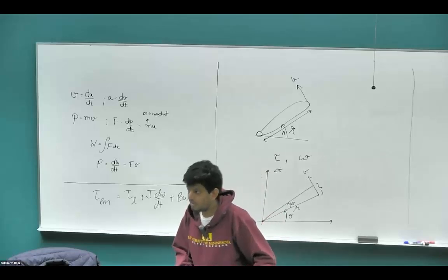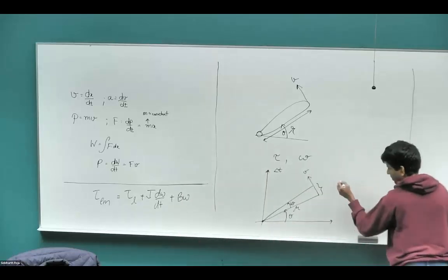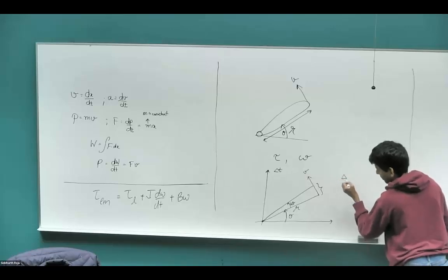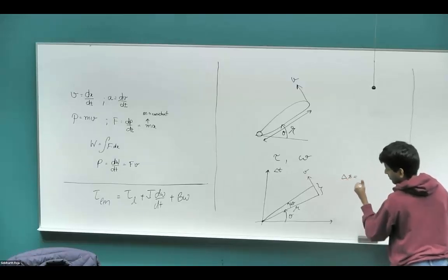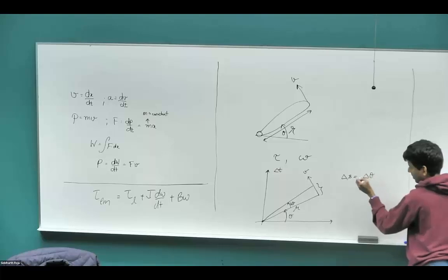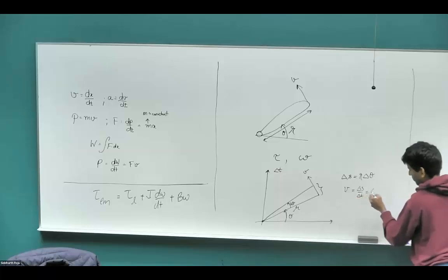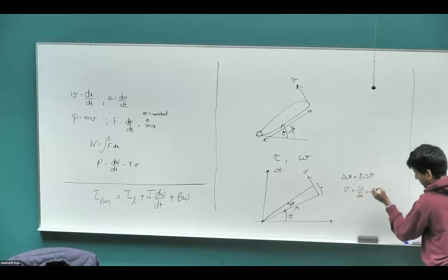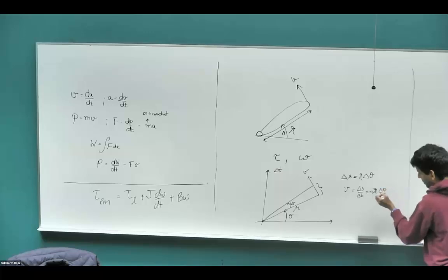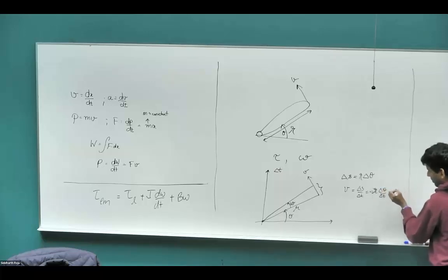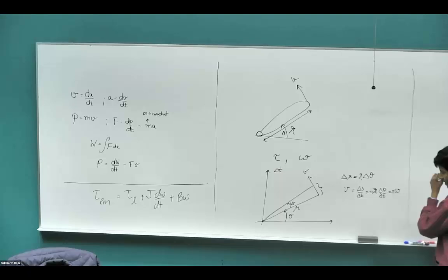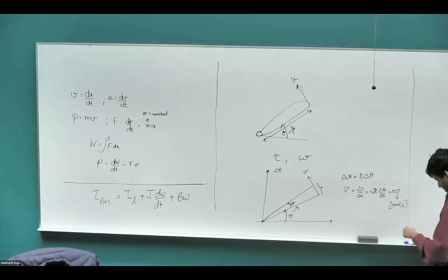So our displacement is just going to be r times delta theta. And from that, we can get our velocity pretty straightforwardly, delta s by delta t. So fundamentally, r times delta theta by delta t, and this we are going to define as a new term, r times omega, where omega is the rotational speed, and the units for it are going to be radians per second. We're always going to stick with SI units in this class.